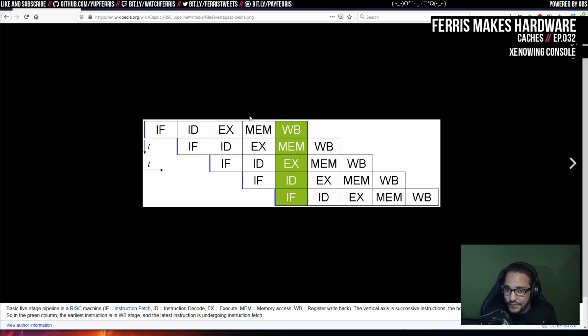Anyway, in order to do that, there's actually another crucial thing that you have to do. Because when you overlap these, you'll notice instruction fetch and memory, for load and store, can now overlap. And currently, I just mux these two things. So there's actually one bus to and from the CPU, but the core of the CPU needs two buses. It needs one to supply the instruction fetch and one to supply a potential load or store within the same cycle.